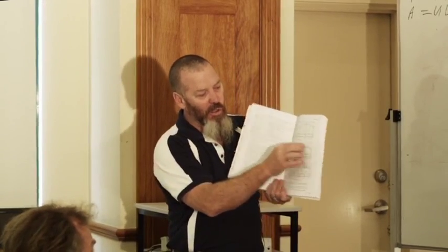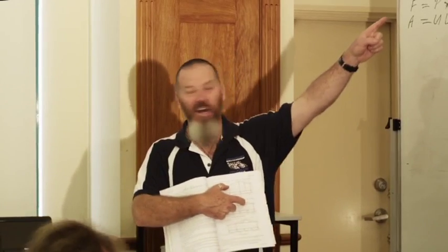The line outlining the ULW on that outside wall is halfway between where the rafter is connected at the top plate and where it is connected at the underpurlin. So again, the formula's there. Half the distance between connections plus the overhang.